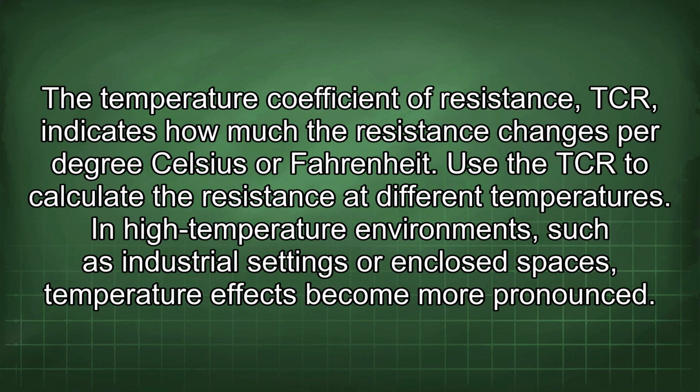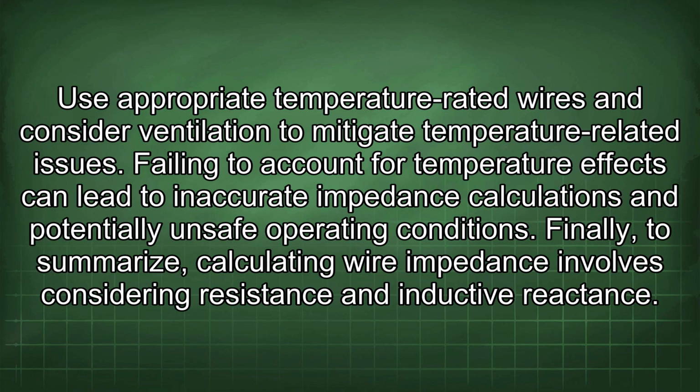The temperature coefficient of resistance, TCR, indicates how much the resistance changes per degree Celsius or Fahrenheit. Use the TCR to calculate the resistance at different temperatures. In high-temperature environments, such as industrial settings or enclosed spaces, temperature effects become more pronounced. Use appropriate temperature-rated wires and consider ventilation to mitigate temperature-related issues. Failing to account for temperature effects can lead to inaccurate impedance calculations and potentially unsafe operating conditions.